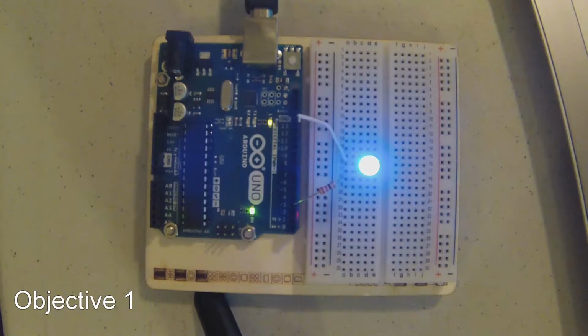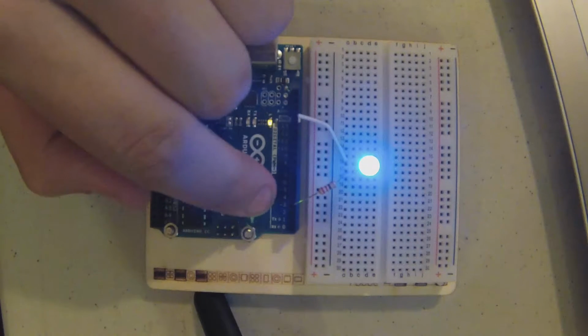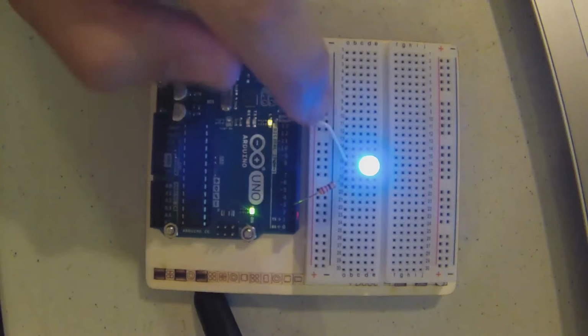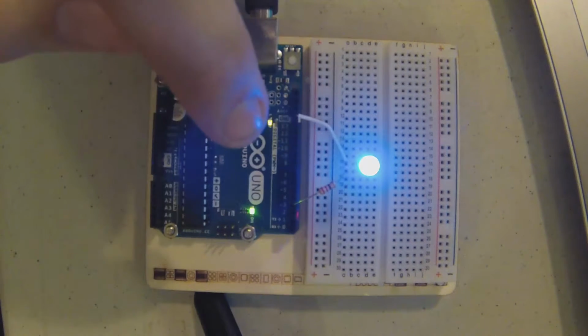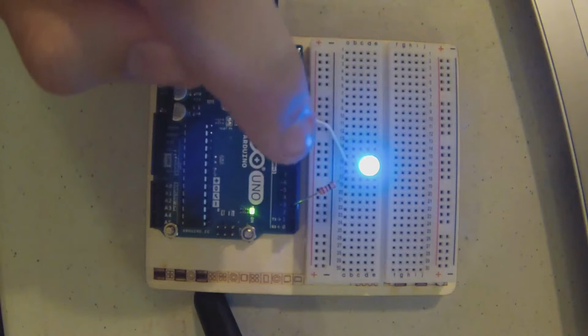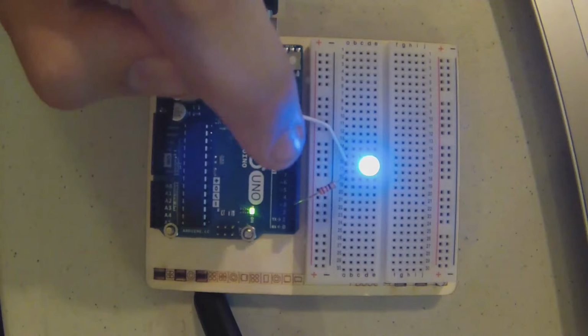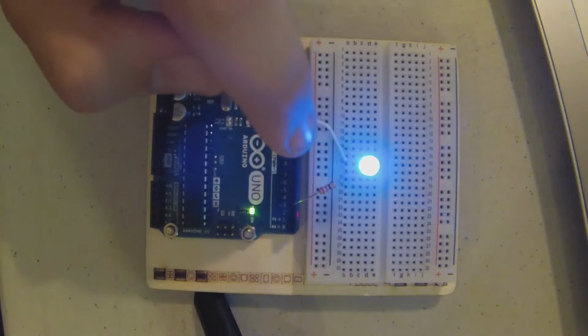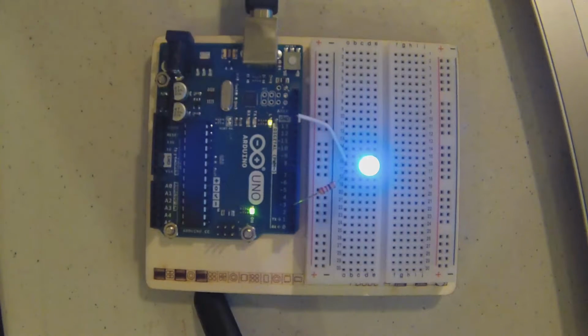Lab 5 Objective 1, 25% brightness. In this objective, we use the pulse width modulation feature of the Arduino board to control the intensity of light emitted from the LED. Going from port 3 to the LED and back to ground, it alters the time that the LED receives voltage in order to very rapidly blink the light and cause a change in the brightness.